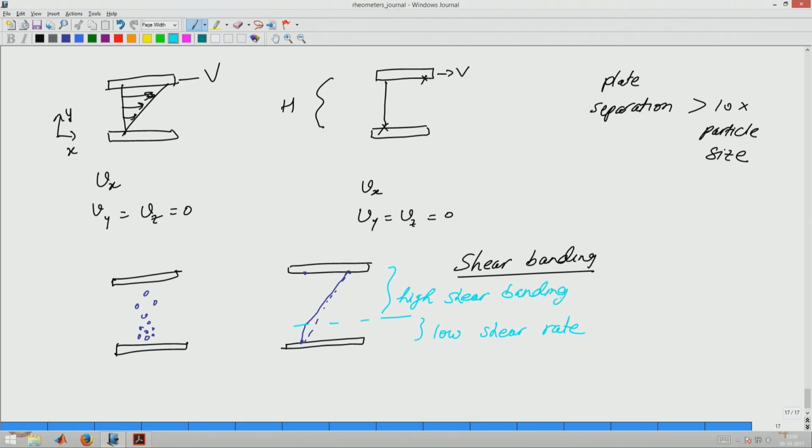One question that always could be asked is, should we be measuring rheology of such materials when there is settling? Because in the end we would like to measure the properties of the material themselves, and if there is settling involved, then clearly we are not characterizing the material, but the settling phenomena. So, one may argue that for this kind of materials you should not really measure properties, because settling is a very significant feature, right.